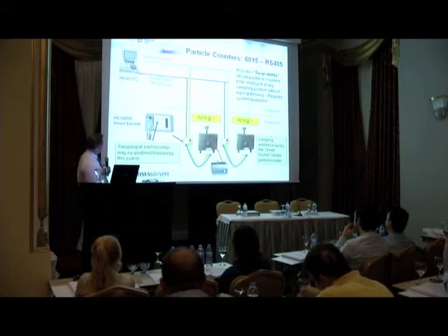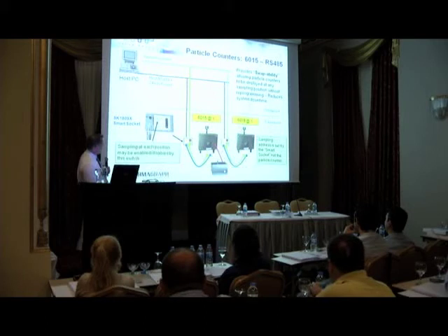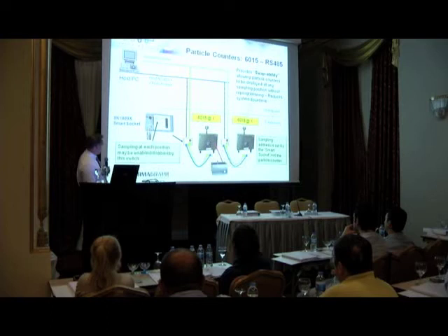When we use RS485, what we do is we put the address into this wall plate here. It's a slightly different version of the wall plate we've seen just now, but that holds the address. The address is common in these counters, so they're all set to address 0. So what that means, if you have a failure of that particle counter, or you wanted to remove it for some reason, you can swap another one in, and your data will always be mapped from that point